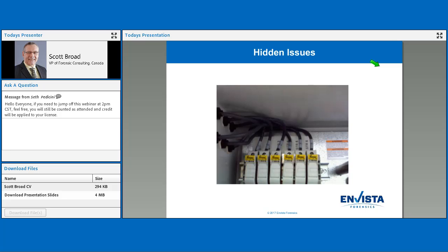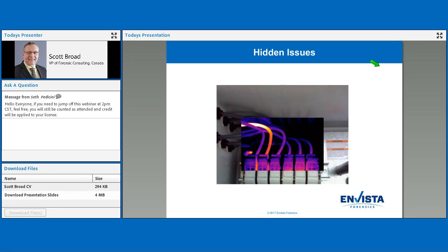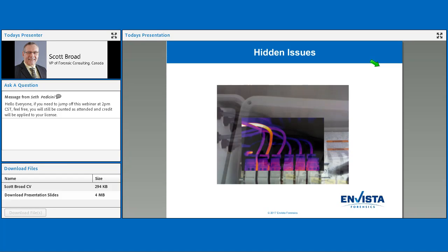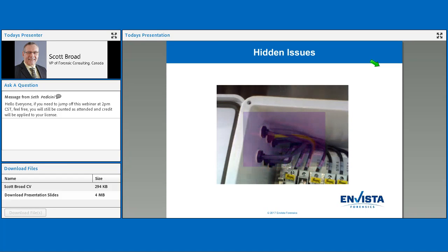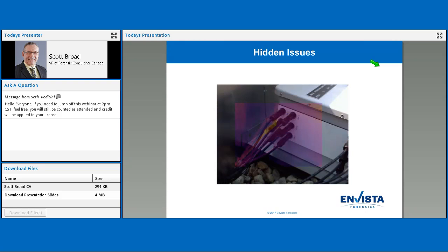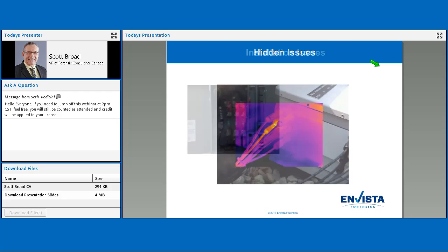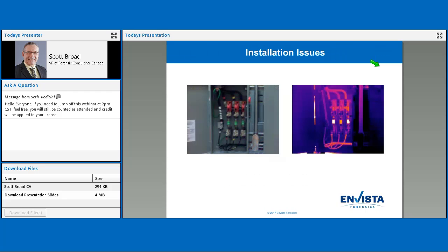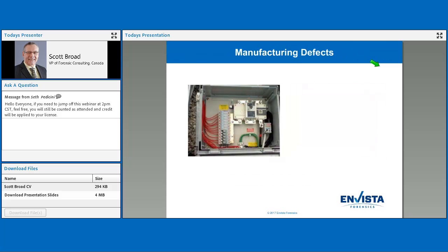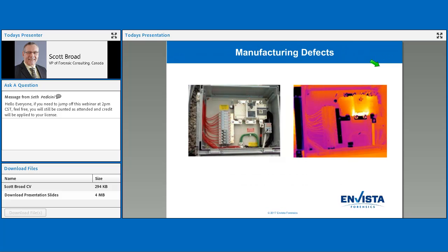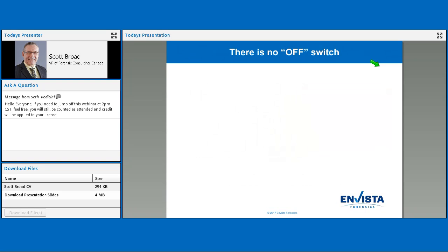You can physically inspect it all you want, but unless you shoot it with a camera, you're not going to find out that we do have an actual issue with this. So if you look at that connection, you'll see it looks like this. And if you look at it further, you're going to see that it connects like this. So we have an issue here. Ultimately, most of the time that we spend looking at our failures, the IR camera is our number one tool.